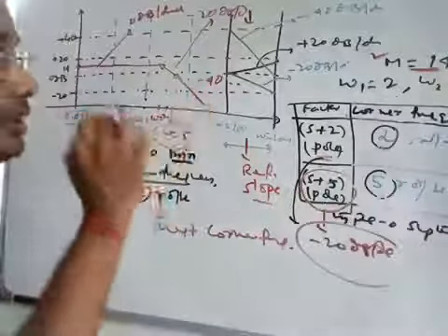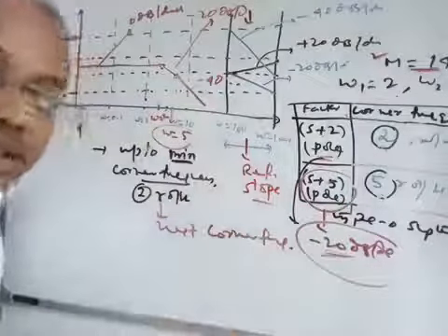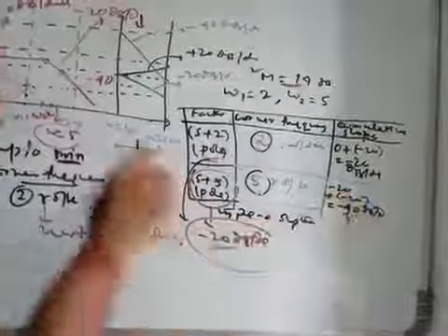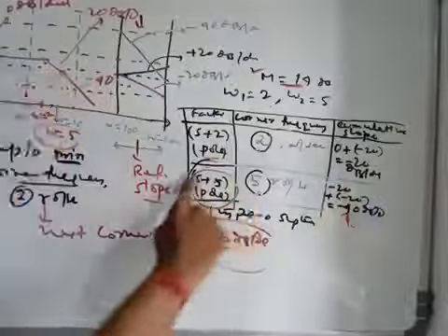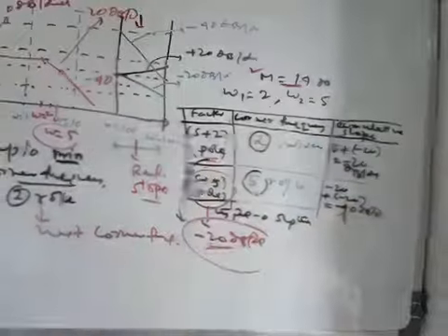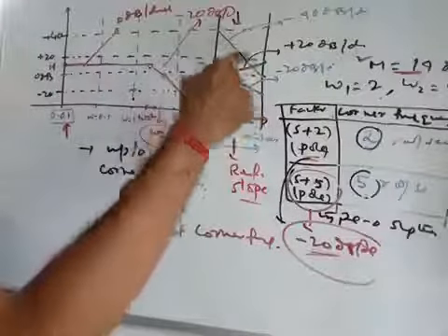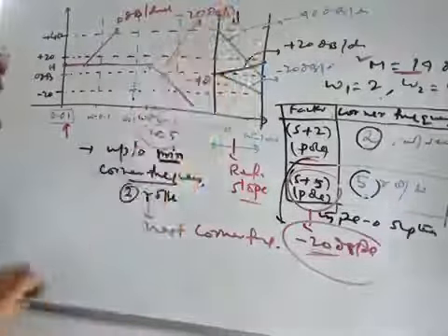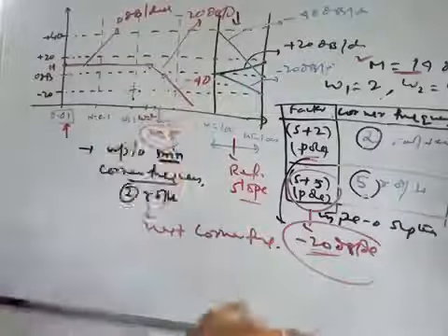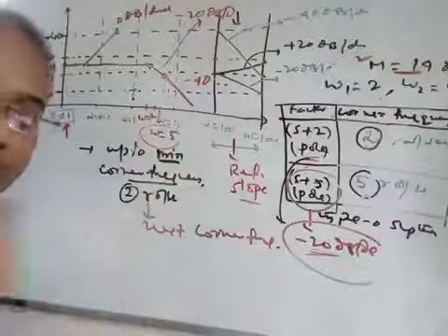Once you reach 5, you see there is again a pole. For a single pole, again the contribution is -20 dB per decade. And what is the cumulative slope you get? The previous slope was -20 dB, and for this pole a -20 dB contribution is added, so you get -40 dB per decade. Once you get -40 dB per decade, you have to draw a line parallel to the -40 dB reference line, right? Just take either a protractor or two scales to get the parallel line. So this is -40 dB. You just extend it.